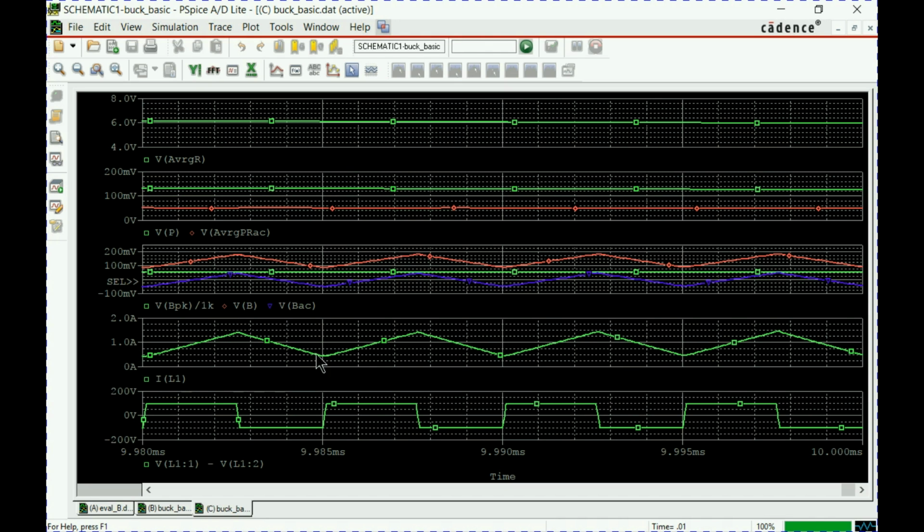Evidently there is a DC component, as it should be, because there is a DC load. And we see here the peak value. This is the green again. The blue one is the AC component of the B. The red one is the total B. Okay, there's a DC component here, but in the Steinmetz equation we cannot use it. We have to use just the AC component. So the blue one is the AC component, and the green is the peak value. And this is again the core loss, and this is the copper loss, and this is then the temperature rise. In this particular case, it came out to be 6 degrees above ambient.